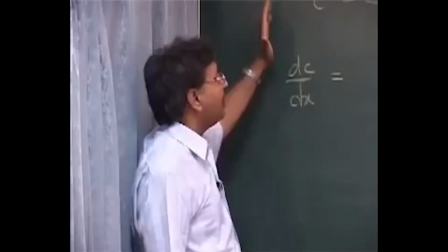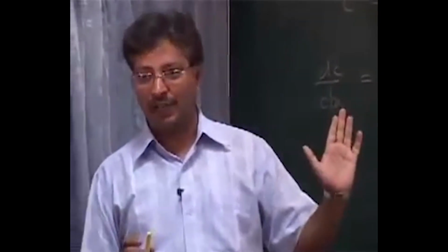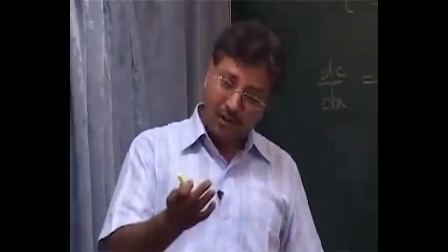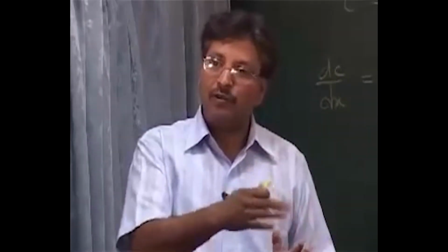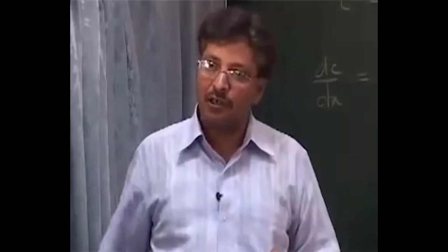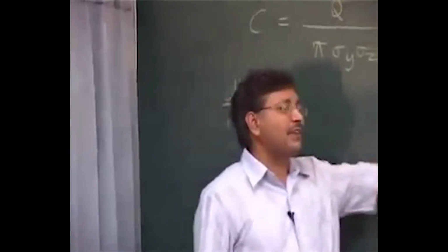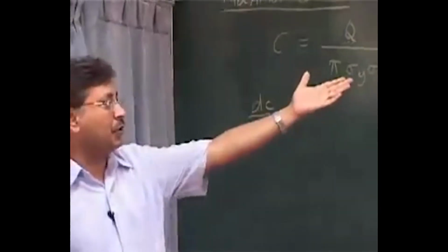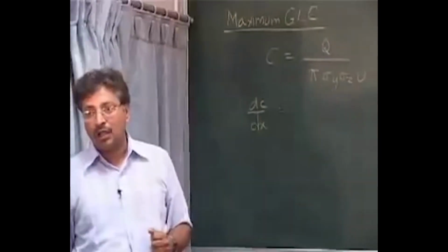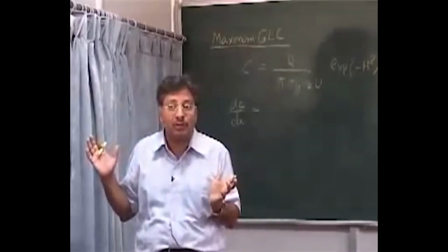So at least I will say this equation is for a particular stability. If the stability is changing and you want to compute hour to hour concentration, what will happen? In the first hour the stability was C, then you compute it for C. You can't just do the work for 1 hour and extrapolate for 24 hours.